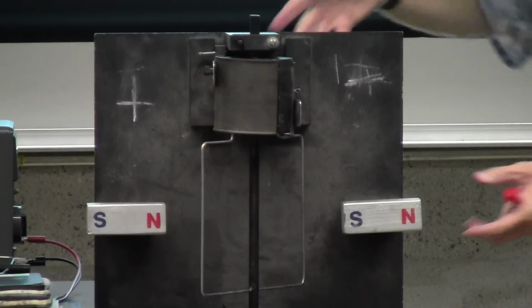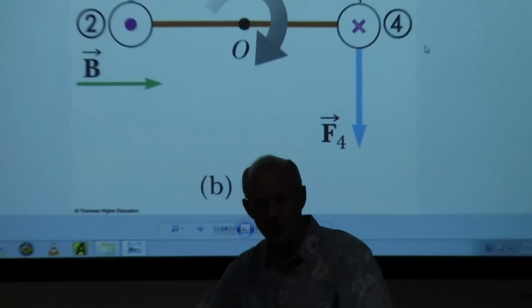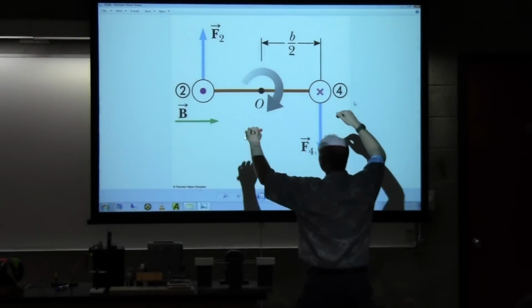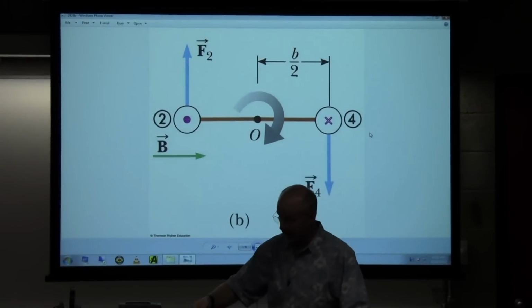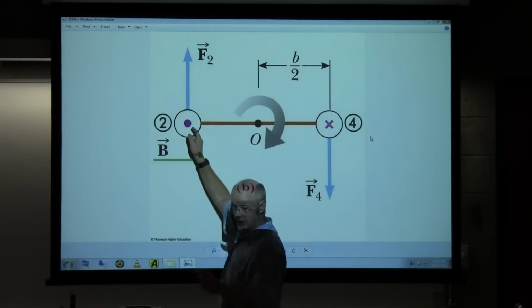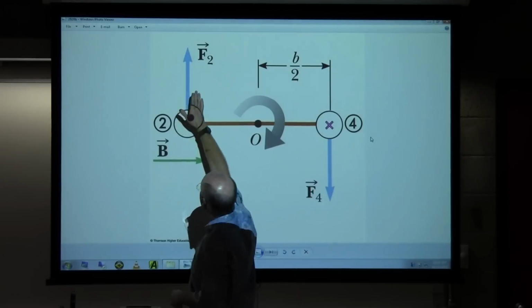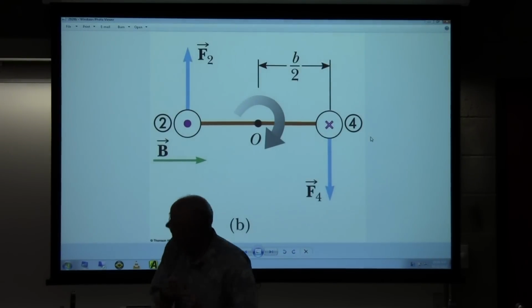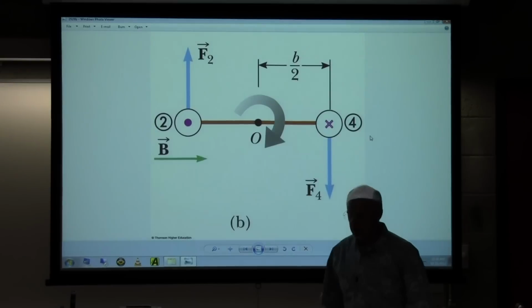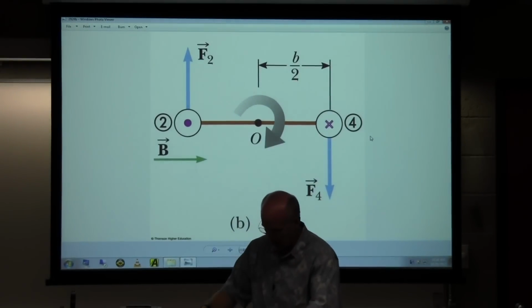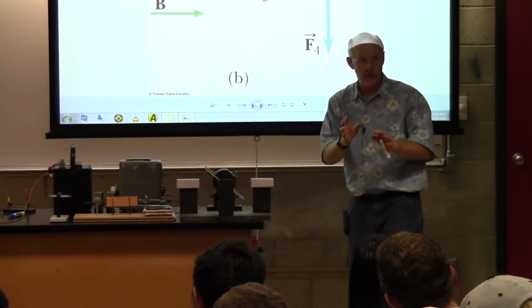And this picture is having you look at it in this direction. And saying, let's look, head into this. And if this wire then is being pushed up, and so the purple color is the current going at you, so here's a current going towards you, then the force, what they call number 2, is up, and this one, the current is going into the screen, force number 2 is going down, and so I would get a rotation like that, at least at first, right?